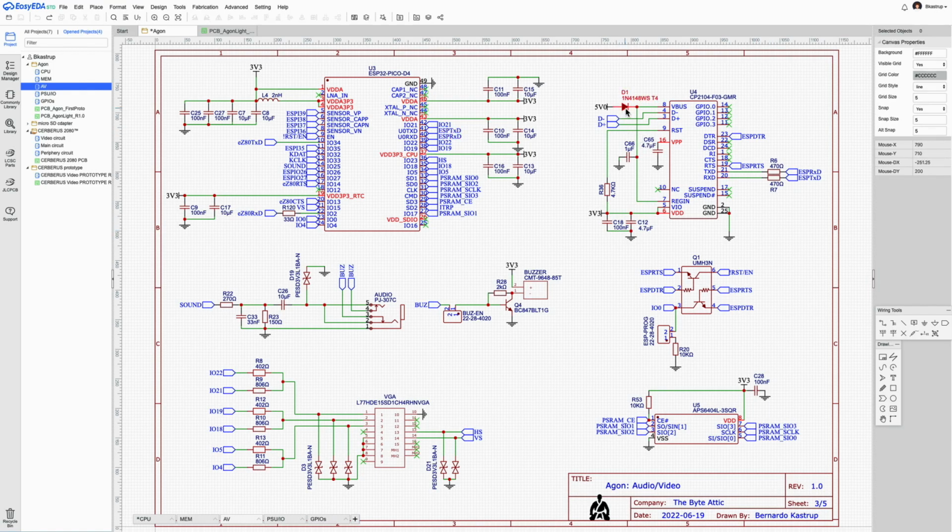This diode here is the most common diode in the world. I'm just using it for the voltage drop. That's all I'm using it for, to reduce the 5 volts to a little over 4 volts for the VBUS voltage of the bridge. Now, to understand why these values, have a look at the data sheet.